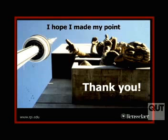Well, I am aware that the question's about how do you plan for the future with development of tall buildings. And I'm aware that some buildings have been wind tunnel tested, particularly if they're doing recladding of the building because of adjacent buildings. I am aware when I was working at the University of Queensland with wind tunnel tests, and I am aware Leighton can speak more to this with his work with CPP and consultants, but I know that wind tunnel consultants typically look at what developments are likely to go ahead in the environment and have a quick placement of a building. It's not difficult to run a wind tunnel study for the base balance crosswind response for an adjacent building that's on the plans. So it's not uncommon for wind tunnel people to do that.